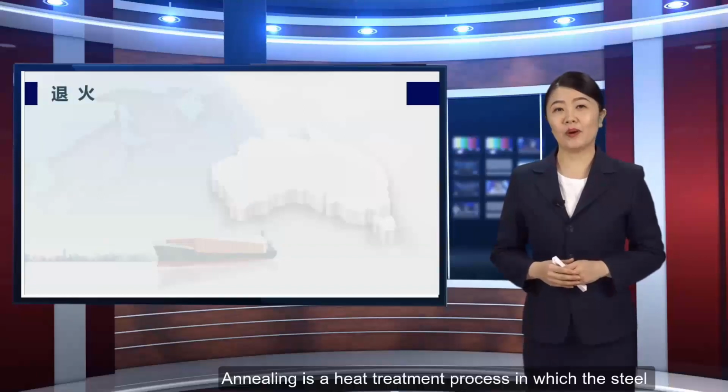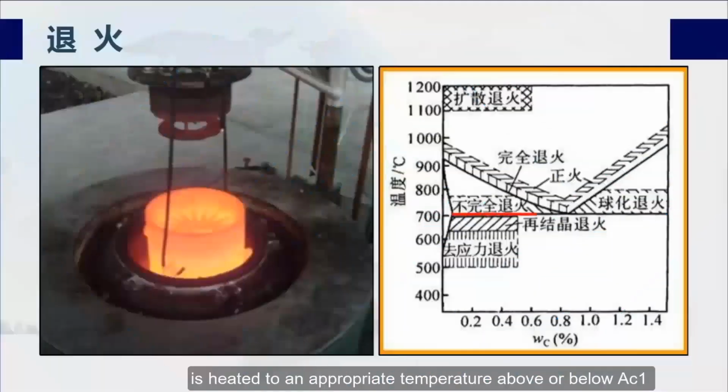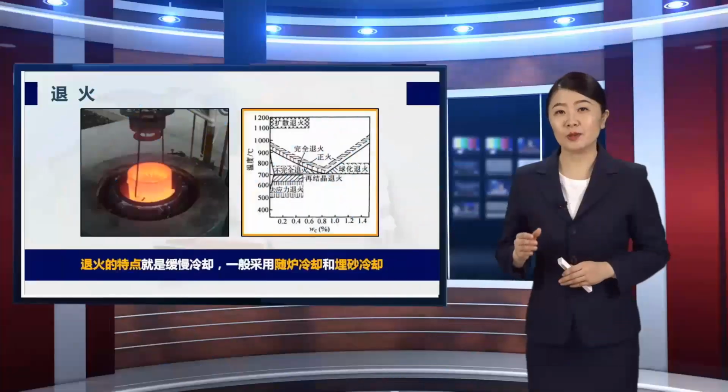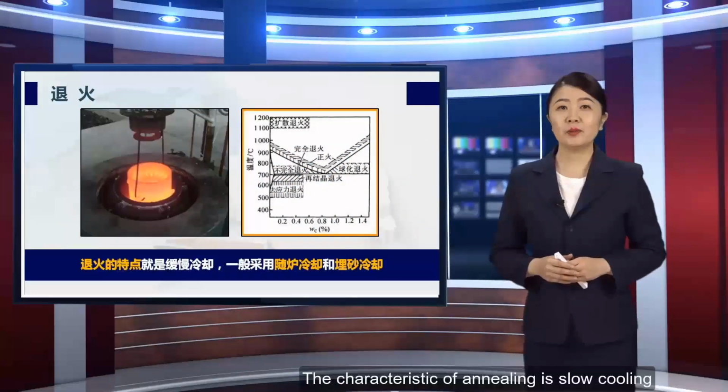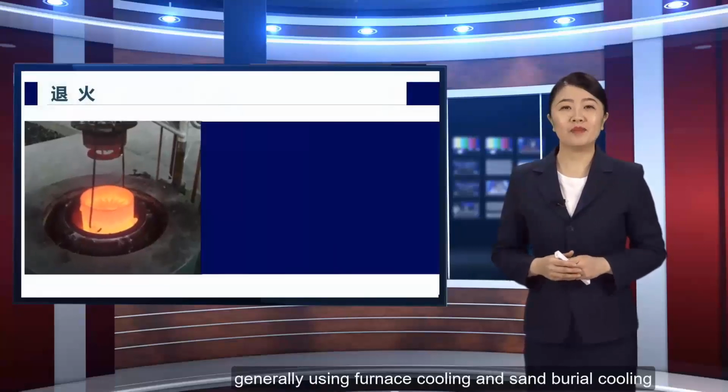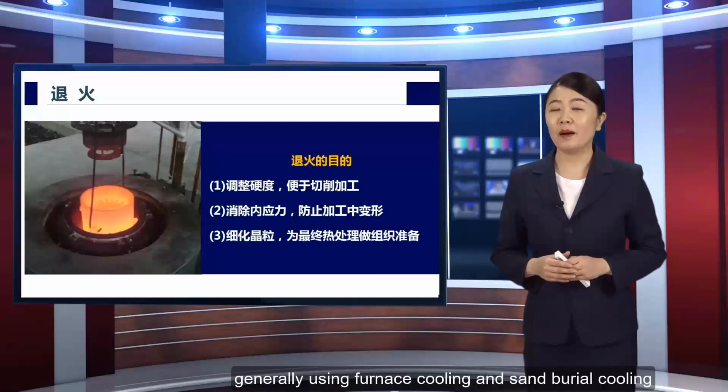Annealing is a heat treatment process in which the steel is heated to an appropriate temperature above or below Ac1, held for a certain period of time, and then slowly cooled. The characteristic of annealing is slow cooling, generally using furnace cooling and sand burial cooling.